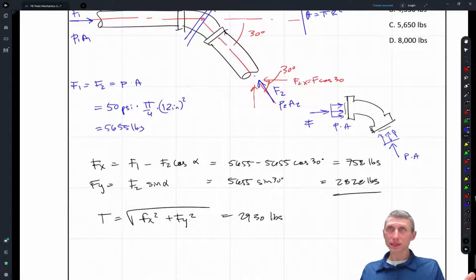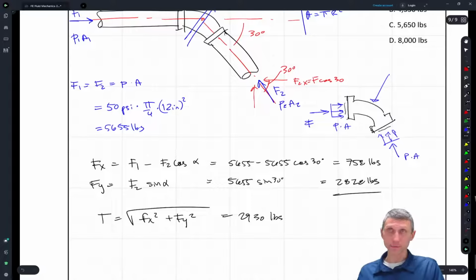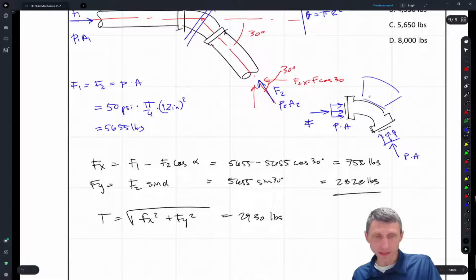So what's the deal? Well, in statics we can't have an unbalanced force. In other words, we need some force here to restrain this. If you look up basic thrust block calculations, that's what they're called. Normally these are going to be concrete thrust blocks, and it'll depend on the type of soil you have. But this is going to be like a concrete thrust block.